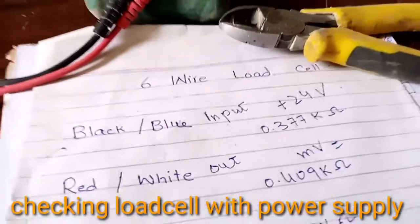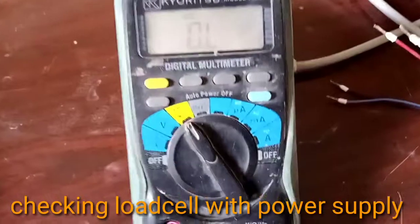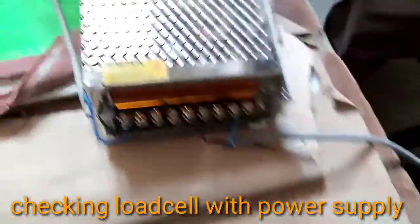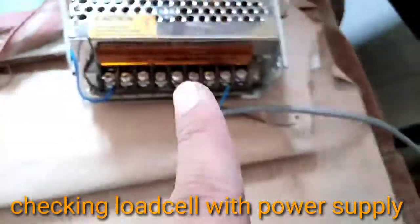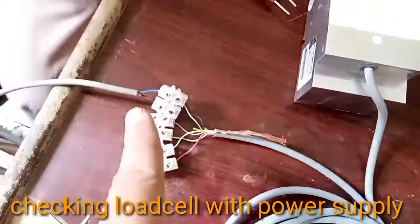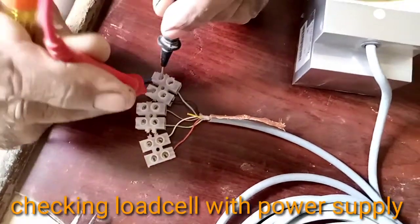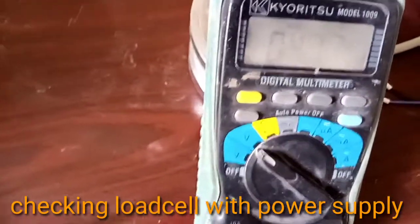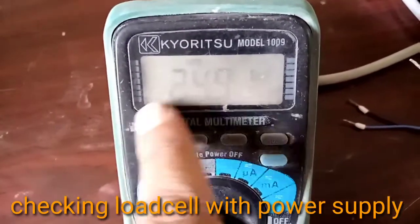Now we give it 24 volt power supply and check with the meter. First of all, turn the meter knob to DC voltage like this one, and please turn on the power supply. You can see the light blinking, and now we can check whether the 24 volt power supply is present or not. Now we check with the multimeter. You can see here, please change its connection, plus 24 volt. You can see that it's present.